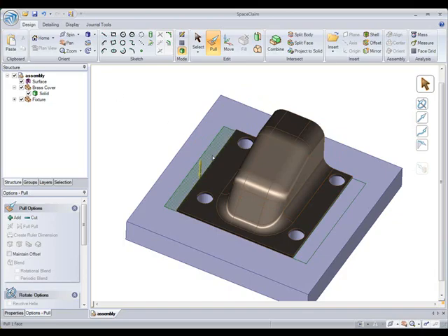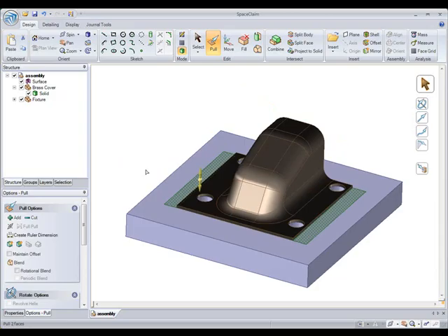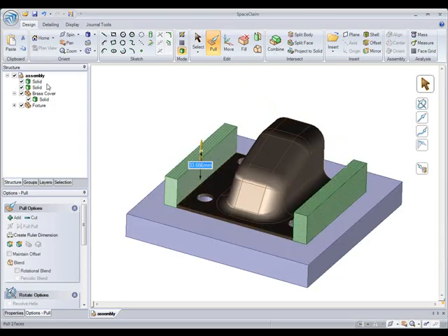So if I select and try to pull it up, normally I would guess that that material would be added to the fixture on the bottom. But notice when I pull it, there's two solids under the active component. So it's really important which component is active when you're making your overall assembly.